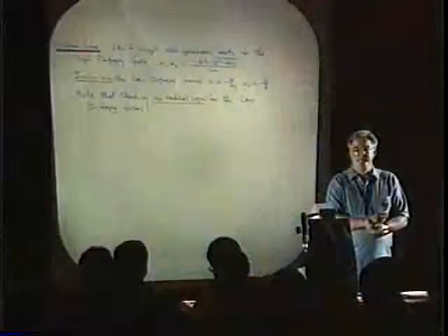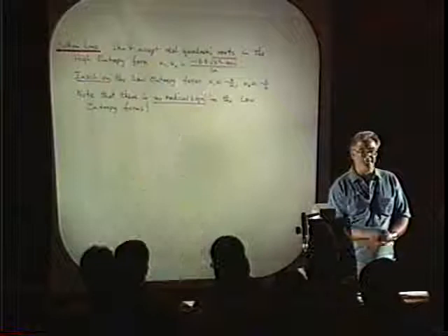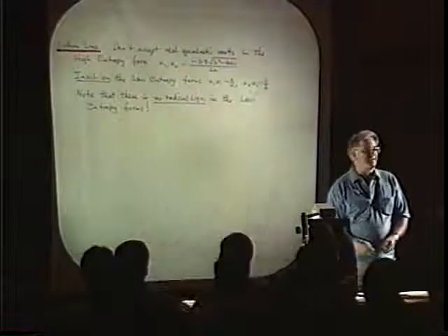Now, there's just one further point about that. You might say, well, we haven't designed it yet, so we don't know what the numbers are, so we don't know whether the roots are real or complex. But another possibility is that the design specification requires them to be real or complex, whichever it may be. Which means that even if you don't know the numbers yet, you know you have to choose them so that it comes out to have the right format of the roots, because the specification requires it. But that's still sufficient justification for making that approximation, if that's what the specification requires.